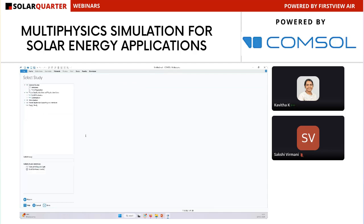For each physics that you choose, there will be different types of study. The primary studies in general will be stationary study or time dependent study, and you will also have other studies based on your physics interface. So these both are the general studies. We will use the stationary study and click done.